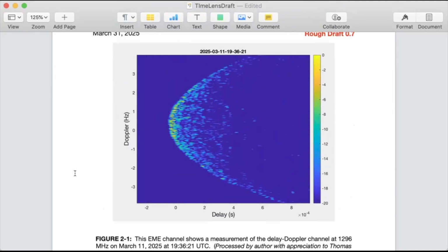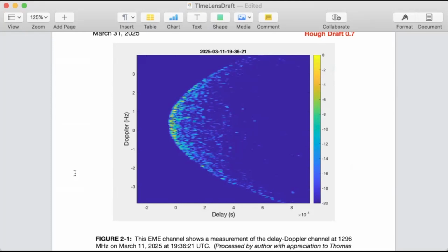And as I wrap up, I'll say what might be an April Fool's joke. There's really only 2 problems with designing an optimized waveform for moon bounce. Maybe there's only 2. So one of the problems is we see in the Doppler spread that the channel is only coherent for a half second, and the round trip time is 2.4 seconds. So we really are very unlikely to know the exact phase of these scatterers. And of course, the cross ambiguity function surface, here we just show magnitude, but it has magnitude and phase. So probably the best hope is to use it non-coherently.